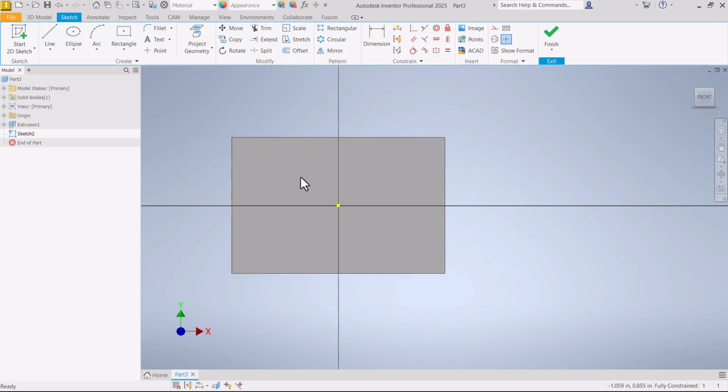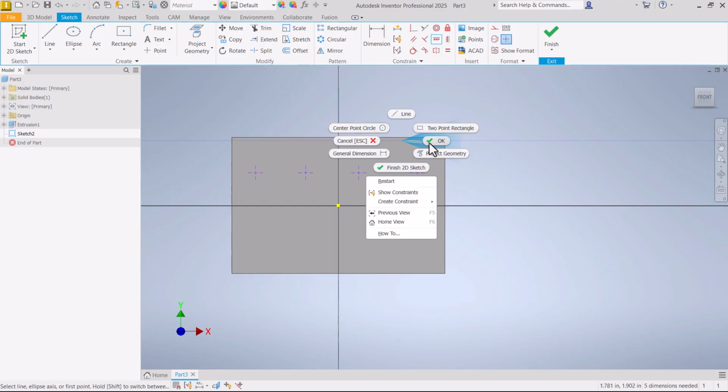And suppose I want to create a series of holes across this part. Now throw some points up here, and I'm going to, again, be sloppy so that they are not lined up with each other. They're all free to move up and down. If I want all four of these points to be in line with each other, I can apply a horizontal constraint to them. First point to the second point. Let's just go back to the first point every time and apply those constraints.